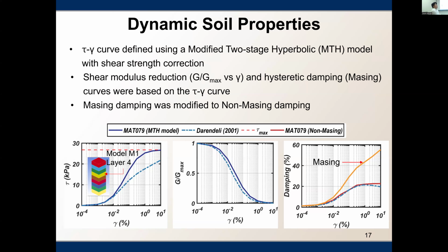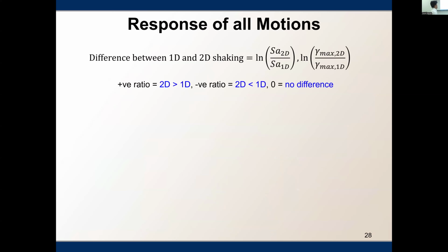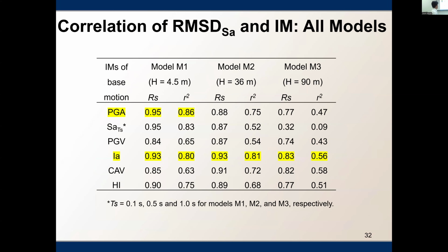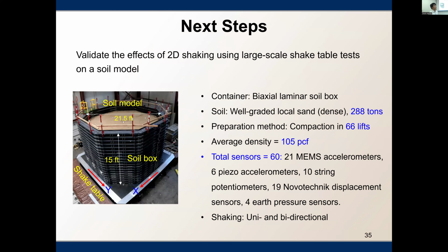Go ahead, Mustafa. In your last slide about your next steps on the soil blocks, regarding the sensors that you put around, as shown in the picture, have you considered the effect of the box itself on the soil and the sensors? Because I guess the center of the soil would be much more comparable to the soil response analysis that you do, but near the boundaries, the effect of the box could be problematic.